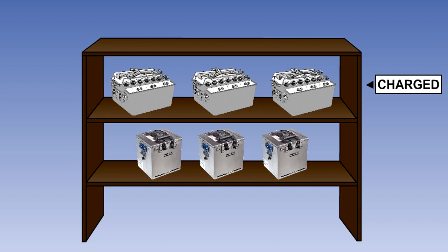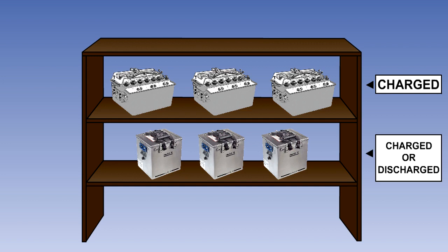Lead-acid batteries are stored in a charged state to prevent deterioration of their plates. NiCad batteries can be stored in a discharged state with no detrimental effect to the battery, and therefore have a longer storage life or shelf life.